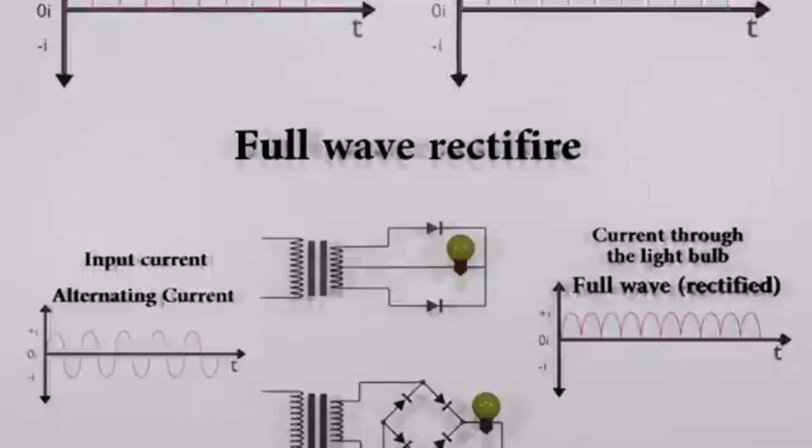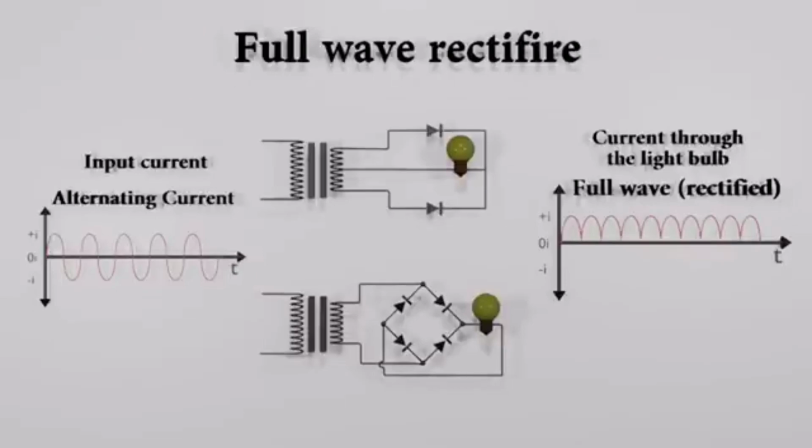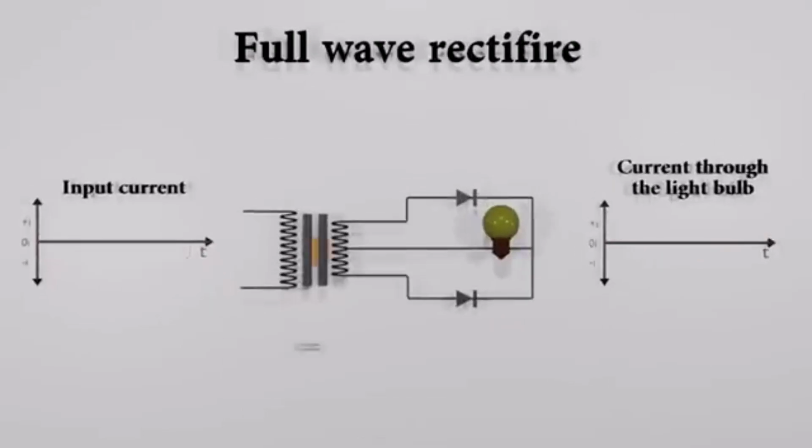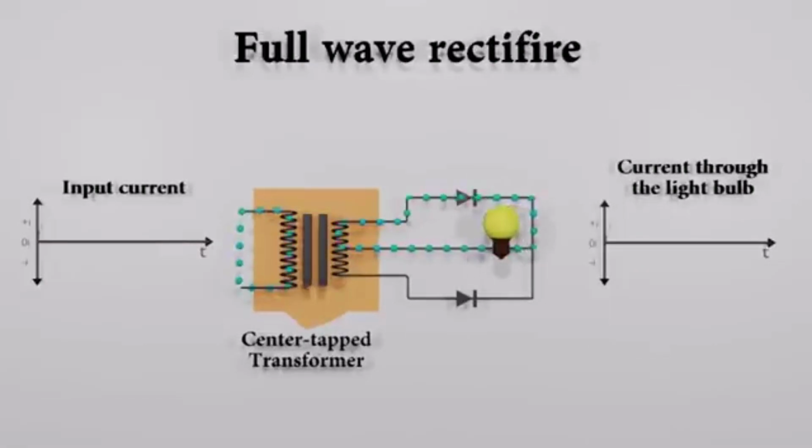There are two major types of full-wave rectifier designs used frequently. The smaller design uses 2 diodes. If the transformer is center tapped, then 2 diodes back-to-back can form a full-wave rectifier. It converts both the positive and negative halves of the input waveform to a single polarity, positive or negative, at its output. By using both halves of the AC waveform, full-wave rectification is more efficient than half-wave.